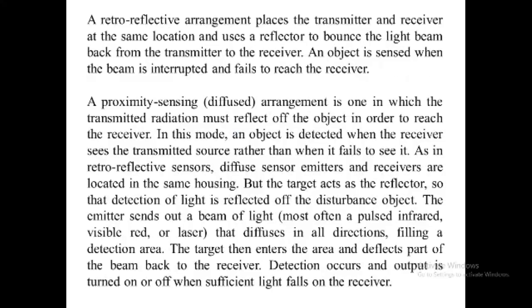They are largely used in industrial manufacturing. A retroreflective arrangement places the transmitter and receiver at the same location and uses a reflector to bounce the light beam back from the transmitter to the receiver. An object is sensed when the beam is interrupted and fails to reach the receiver.